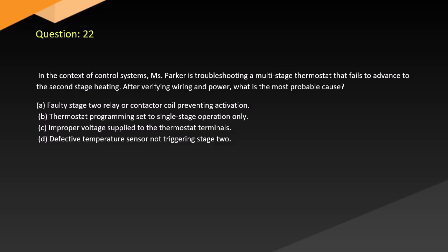A. Faulty stage 2 relay or contactor coil preventing activation. B. Thermostat programming set to single stage operation only. C. Improper voltage supplied to the thermostat terminals. D. Defective temperature sensor not triggering stage 2.